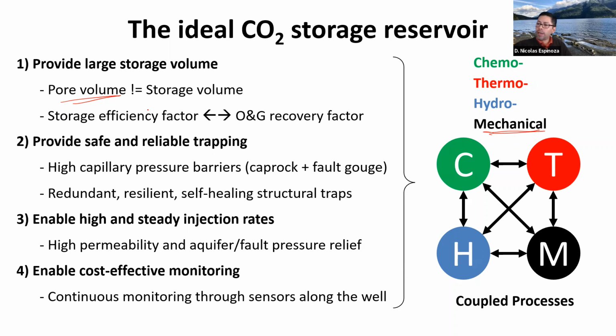Also, we need to provide reliable and safe trapping. And that's going to depend on the barriers that we have in our storage system. This could be a cap rock, or it could be a fault. And that's something that we have to understand too. Similar to what happens with oil and gas, if we inject CO2, we're going to have a buoyancy pressure that we need to make sure is not enough to go through some of these barriers, or is not enough to reactivate some faults or fractures.